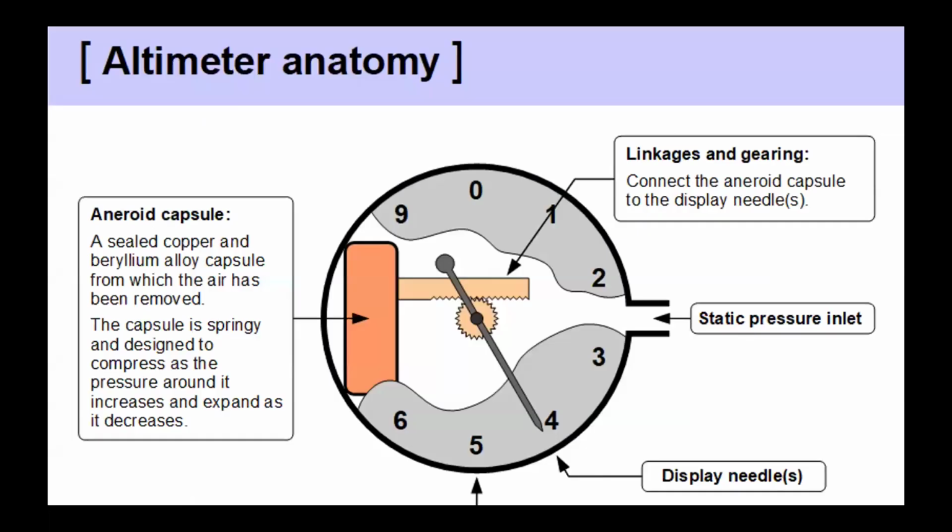So going into the altimeter. The altimeters are calibrated at sea level under standard atmospheric conditions. They have errors under all other conditions. So the sensing mechanism shown is the analog approach. We have a device that's called an aneroid capsule. This is a sealed capsule, and it compresses as the air pressure increases around it, and it relaxes as the air pressure around it goes down.